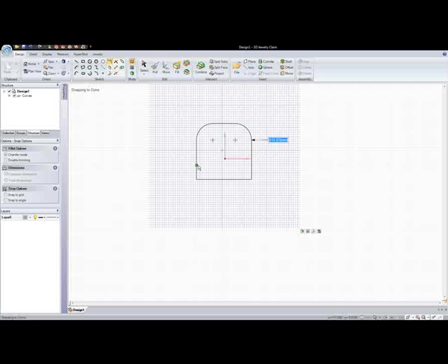If I select on chamfer mode, I can left click on a starting point, but instead of rounding the corners it gives me a straight beveled edge. And I can left click at an end point, and now we got a tapered edge. Next, I'm going to show the disabled trim. By selecting on disabled trim, I can now round my corners. However, I will not delete the line. It will not trim away the excess line.